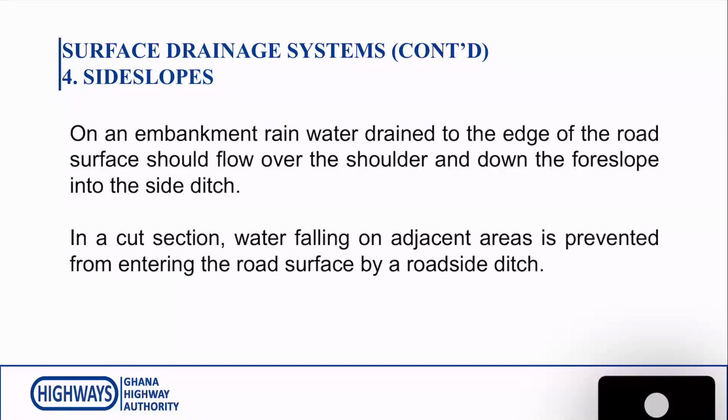So if you have an embankment, it's important to have the shoulder properly installed such that when it rains, the water runs over the pavement surface, over the shoulder, and down the side to a ditch. And in a cut section, you are sure that the water coming from the adjoining lands and from the road is trapped in the roadside ditch and doesn't get into the pavement.